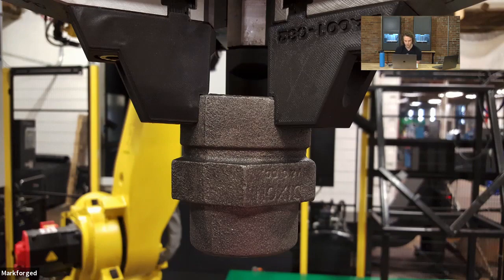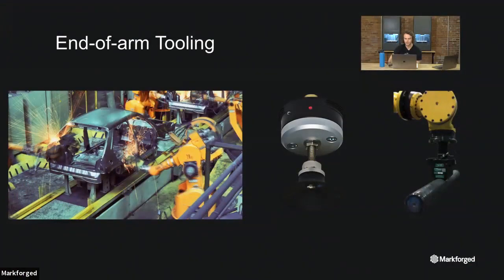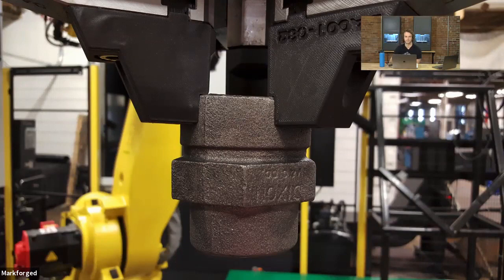And so although there's all these different types, they all have one main thing in common, and it's that they're typically very expensive. And the reason why is because grippers are manufactured in low volumes. So this means that first you have to design the part, and then if it's getting sent to the machine shop, you have to process the part in CAM, and then you have to send it to the machine shop to be machined, where it will probably wait in a queue. So that's skilled labor to be machined. And so then if a part breaks on your line, if you have an end effector that fails, then it can be a lengthy downtime because you have to wait for the part to be machined again if you don't have spares.